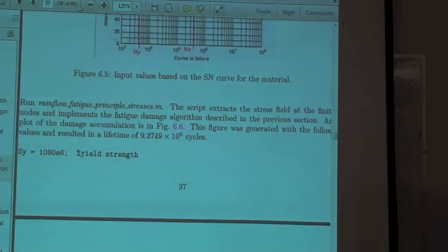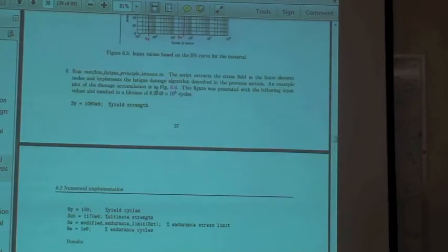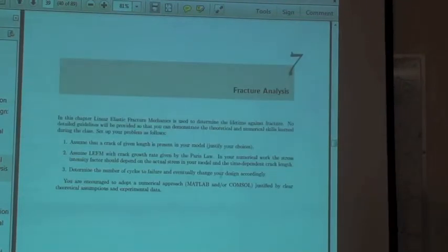So that's essentially the whole fatigue analysis. And then you could calculate how many life cycles you want it to run and all that. And then for the fracture mechanics, we let them do that using a Paris law. We identified the critical zone from the fatigue analysis, where we have the maximum damage. We could actually put a crack in there and then see how far it propagates with the Paris law, right? Okay. Yeah.